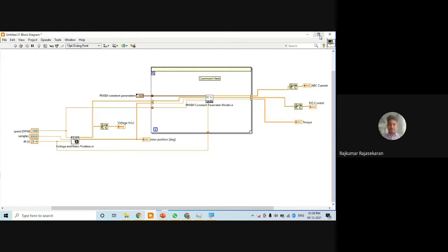They would require support like this. Several companies would require a real-time test platform as well, so solutions should be required in that case. They're not going to stop with the simulation in the software alone. They would require implementing it the same way, and furthermore doing integration testing, to check how the hardware will respond in real time. So it does not stop with computer execution; you could do it with RT, a real-time computer, and also with FPGA-based hardware.